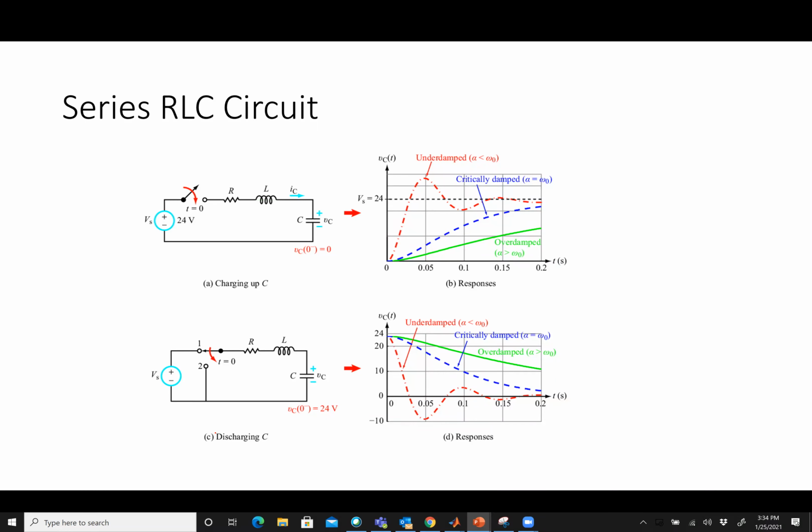So there's the series RLC circuit, there are all kinds of different circuits. Essentially, what we see is kind of what we already talked about here. In the series RLC circuit, if it's underdamped, alpha less than omega naught, I get this kind of overshooting, where this guy comes up and overshoots and then comes back down. Then as I go to an overdamped scenario, he's usually slower to rise, but he's not as wild. That's a very non-technical term, but a lot of times I consider this underdamped response to be, quote unquote, wild. And there are reasons why I call it that.